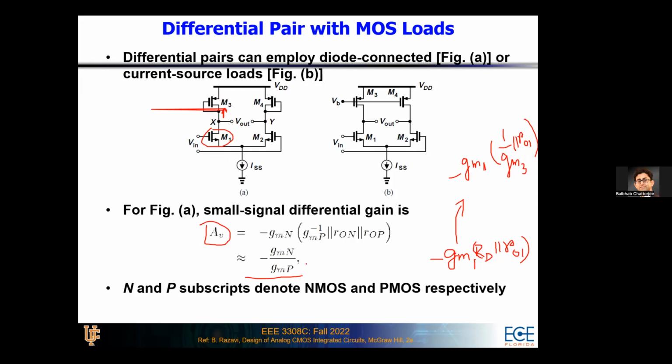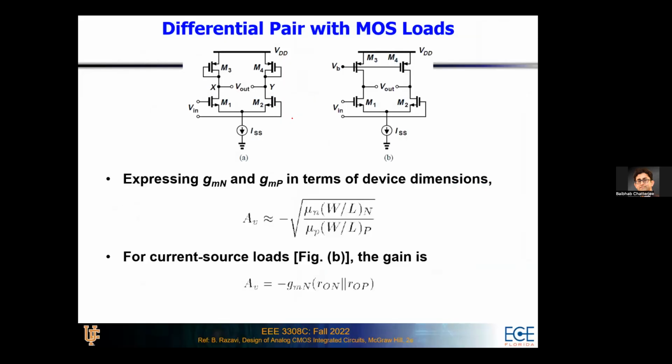So in your homework problems, did you ever see the GM of one transistor being hundreds of millisiemens and the other one being microsiemens? You did not, right? And that's only because the W over L of the transistors does have a physical limit when you actually place them in a chip, in a circuit. So you cannot have a very high gain for this particular circuit, but we already know what is the solution to that, how to have a higher amount of gain.